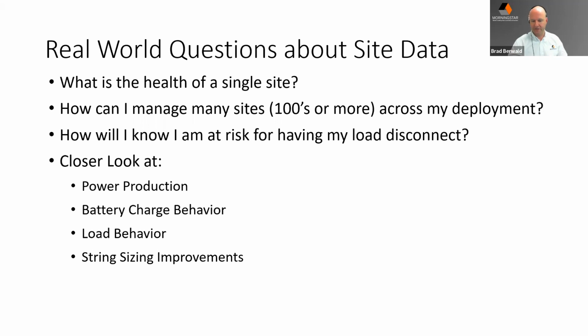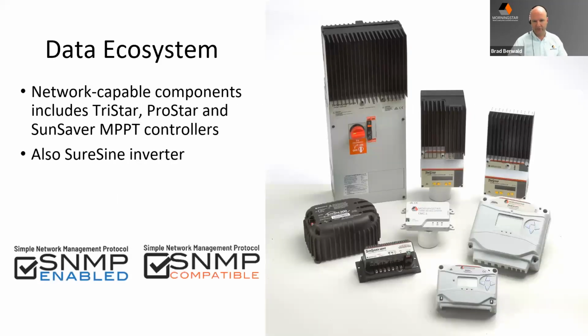So thinking about those types of deployments, it also gives you a closer look at things like power production, how much you're generating, the battery charge behavior, is it properly cycling the battery? The load behavior, is your load a consistent draw, or is it something that turns on and off? And how do you measure what that actually is in the real world? And then we can also incorporate that data into some of our improvements in how the strings are sized, whether it's more series or more parallel, and the types of modules you're using that reap the biggest benefits from an MPPT controller. And we'll talk about that a little bit here in the future.